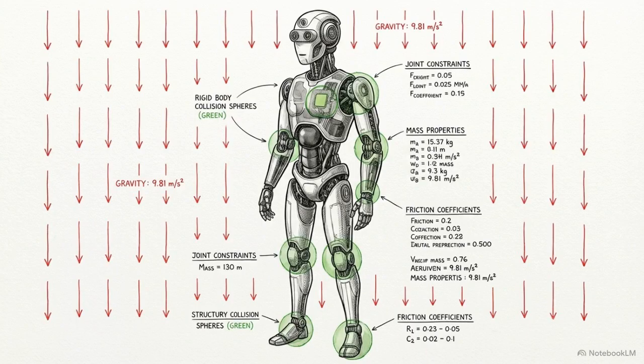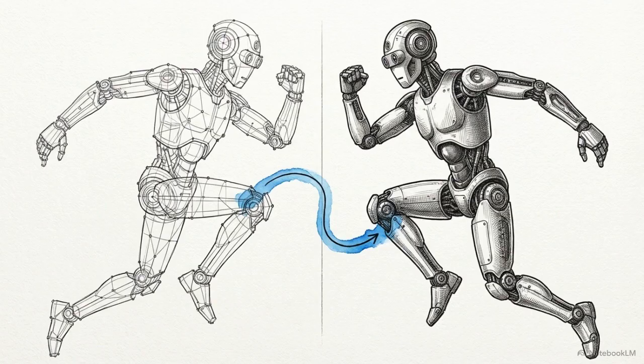Because this happens inside the Isaac Lab framework running the Newton physics engine, these synthetic trajectories strictly obey real-world gravity, mass, and rigid body collision dynamics. This enables accurate sim-to-real transfer. The low-level motor intelligence trained in the simulation translates zero-shot to the physical hardware.